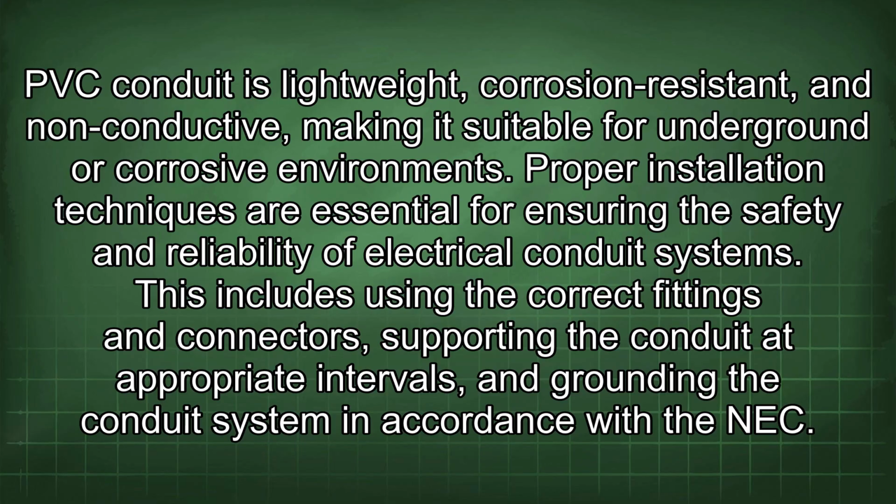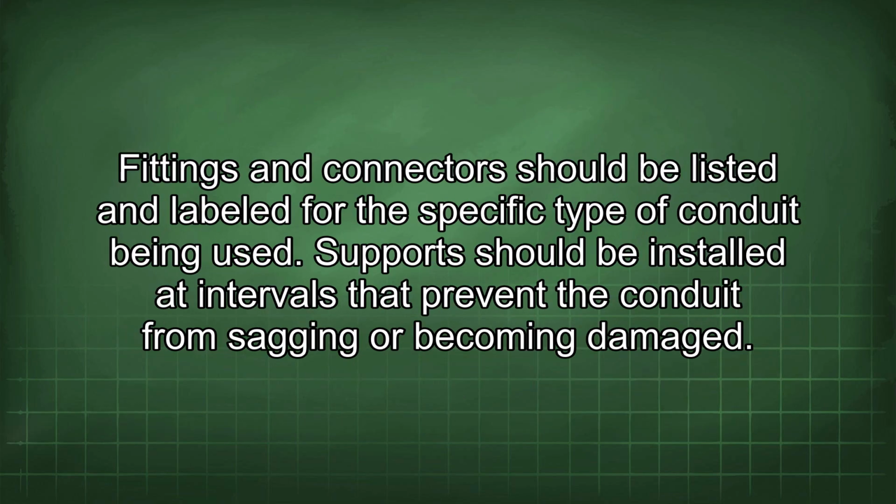Proper installation techniques are essential for ensuring the safety and reliability of electrical conduit systems. This includes using the correct fittings and connectors, supporting the conduit at appropriate intervals, and grounding the conduit system in accordance with the NEC. Fittings and connectors should be listed and labeled for the specific type of conduit being used. Support should be installed at intervals that prevent the conduit from sagging or becoming damaged.